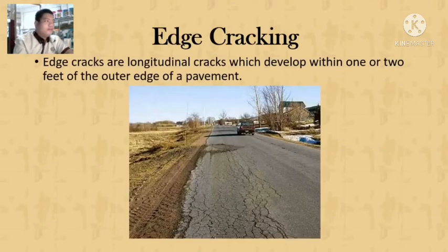Edge cracking. Edge cracks are longitudinal cracks which develop within 1 or 2 feet of the outer edge of a pavement. These cracks form because of a lack of support at the pavement edge.